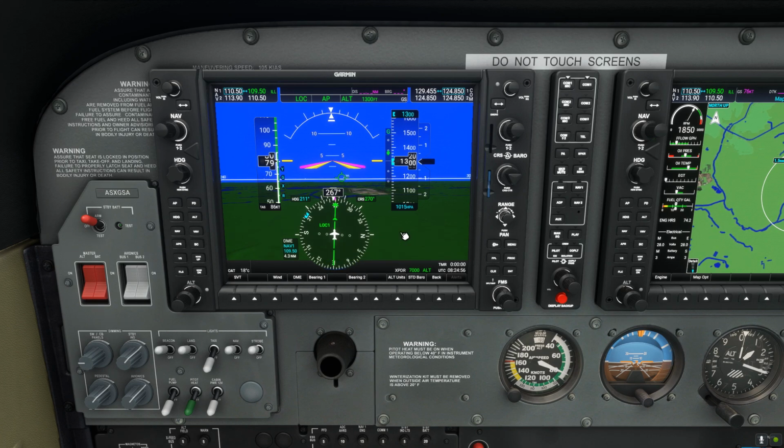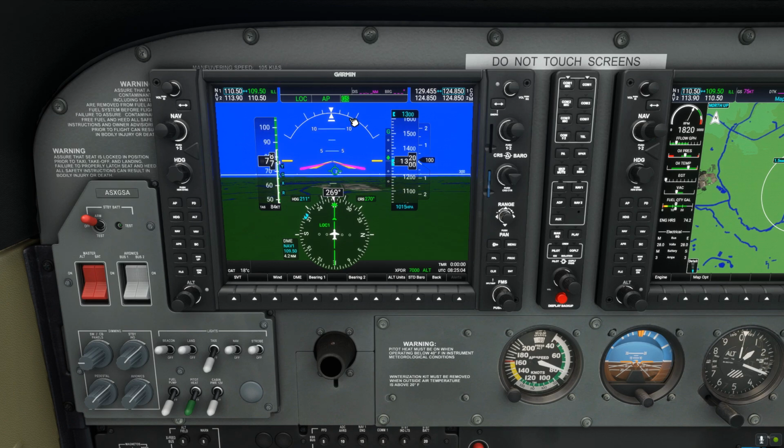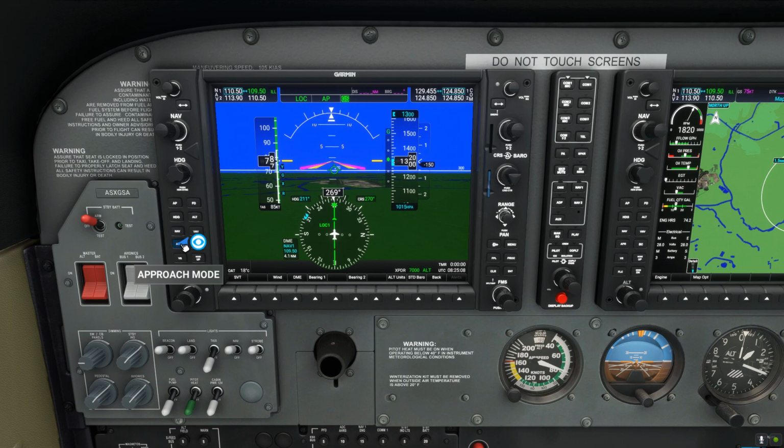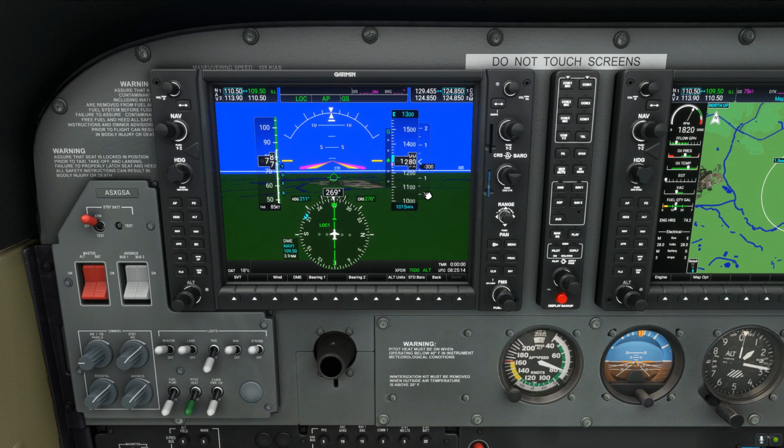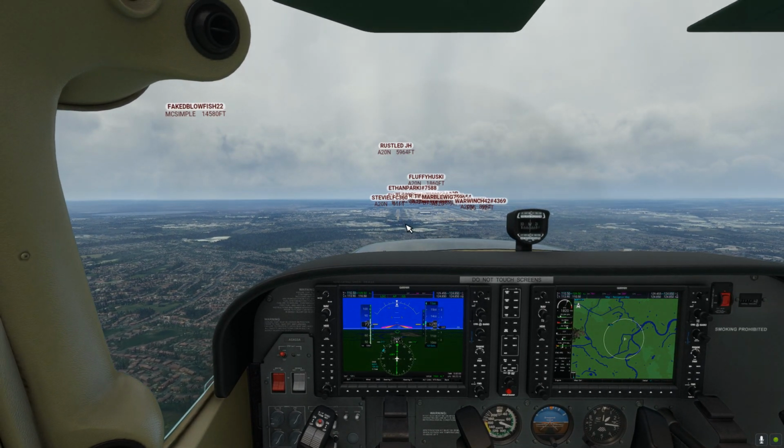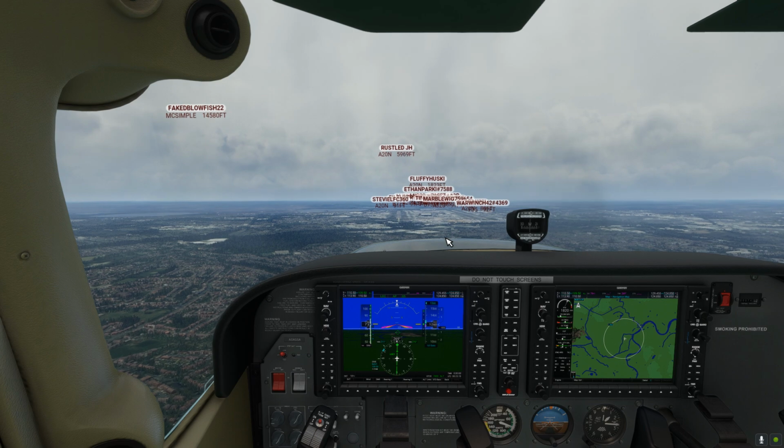Lower my throttle again just a tiny bit, because I'm going to go to flaps 1 now, stage 1 flaps. It's going to start descending any second. See, glide slopes, I've not pressed anything else, because I pressed my approach mode button before, when a course deviation line came in, it's actually also locked onto the glide slope for us, and will bring us down to runway 27. Isn't that fantastic?